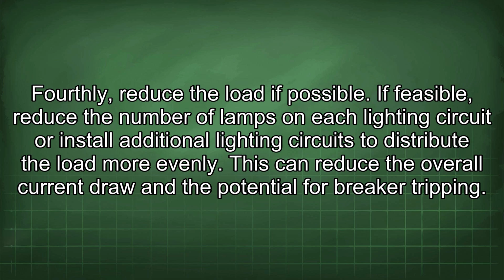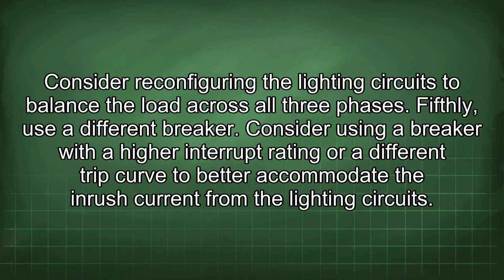This can reduce the overall current draw and the potential for breaker tripping. Consider reconfiguring the lighting circuits to balance the load across all three phases. Fifthly, use a different breaker.